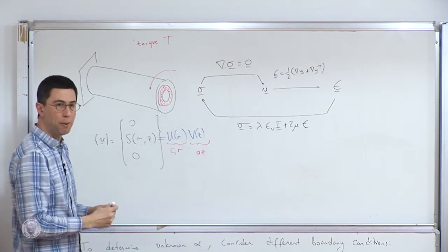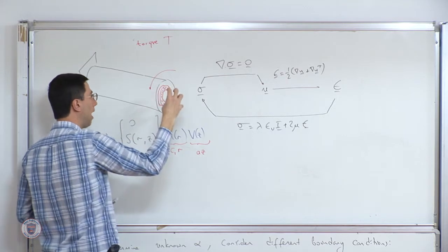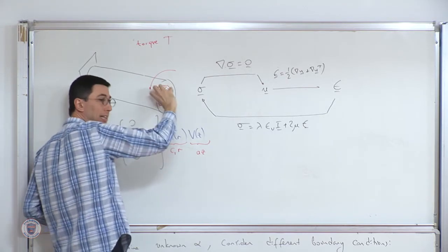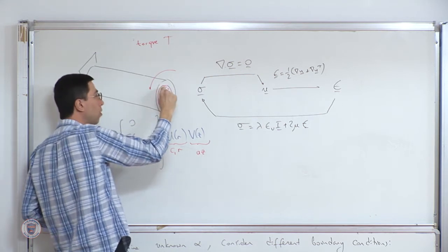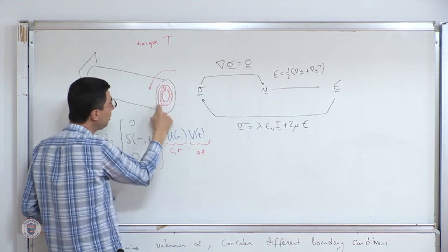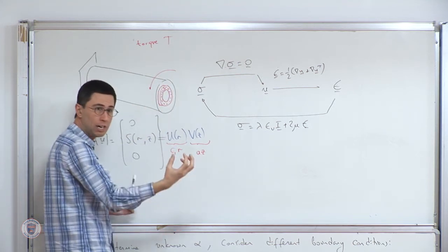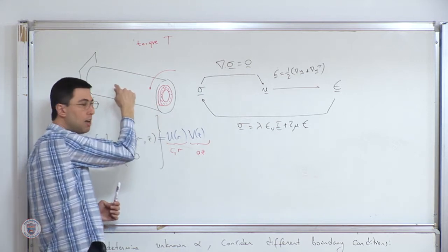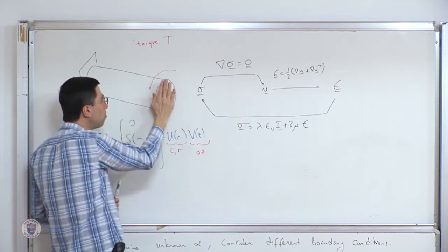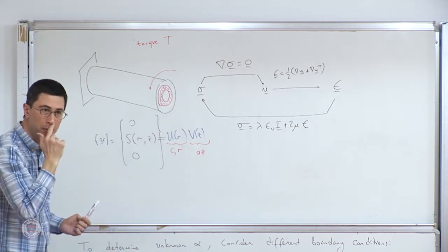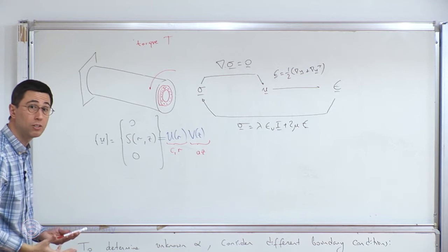There is some apparatus at the end. I hold this apparatus, the red disk, and I rotate that disk, and I apply the torque on that red disk. The red disk contacts the black cylinder only in a certain region. That's where the traction will be, or the stresses will be transmitted to the cylinder. So the nature of the stress distribution where the red disk contacts the surface of the cylinder could be quite complicated.